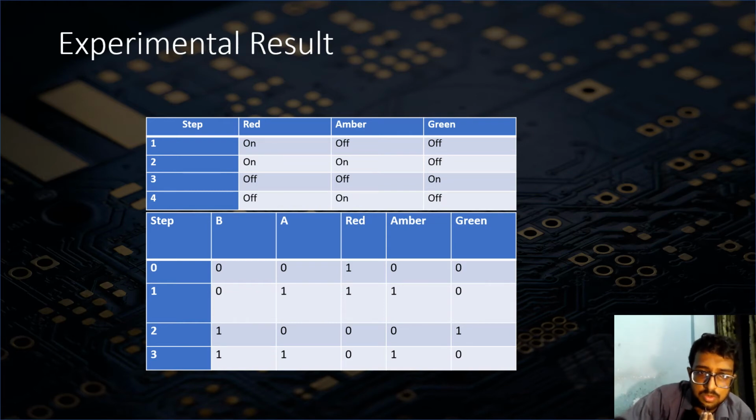Next, we move to the amber, and once again we look at the truth table. It would appear that the amber always follows the logic level of the A input. The green is a little trickier, as there is only one combination where we should illuminate the green. That's when A equals 0 and B equals 1. But we have two choices here.